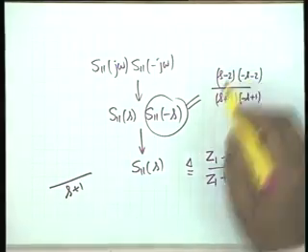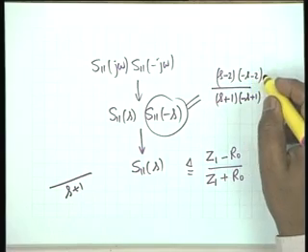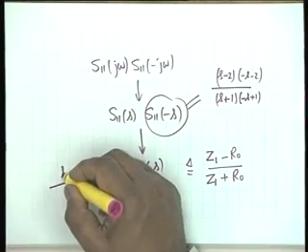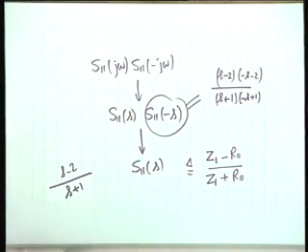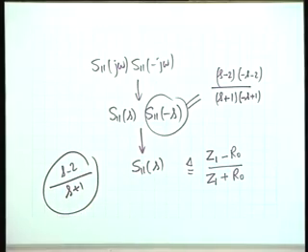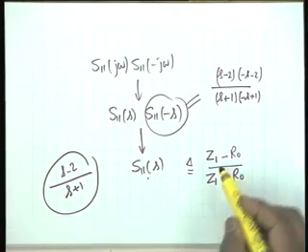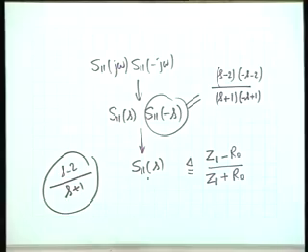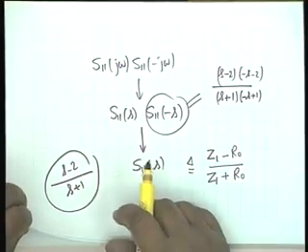Z1 equal to R0 defines the zeros, and so you have a choice. You could either choose S minus 2 or you could choose minus S minus 2. Alright, let us say S minus 2. Then this is your reflection coefficient S11, and from the reflection coefficient you can find out Z1, the input impedance.